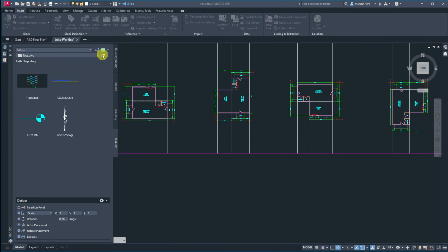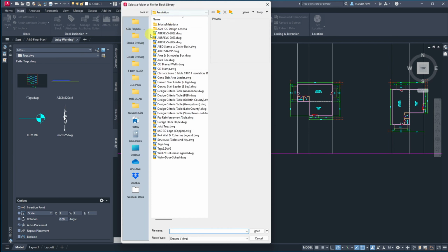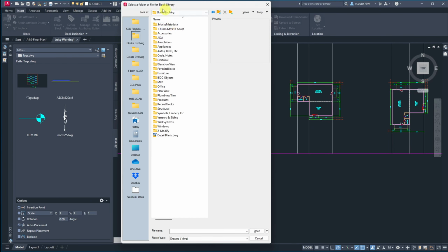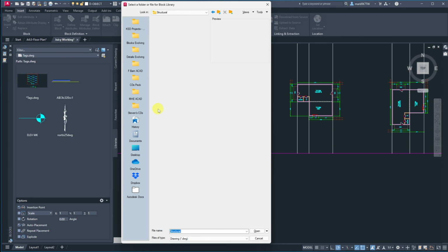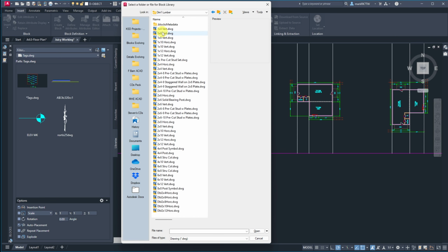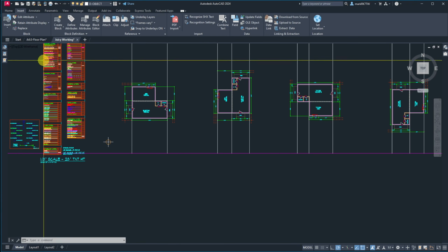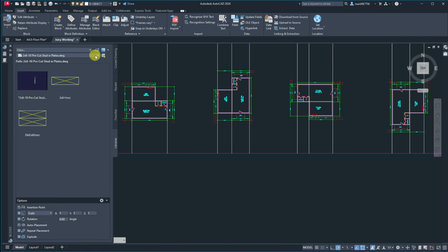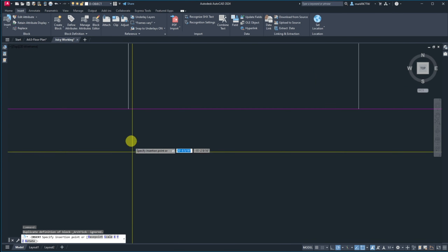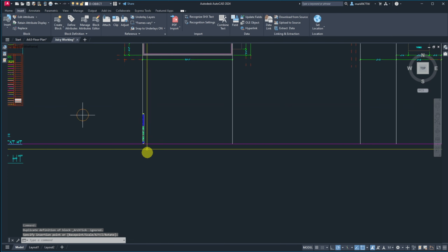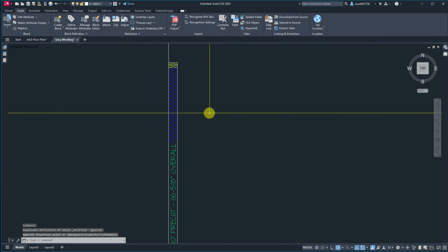So nothing was there, so I'm going to go to library, which now I'm going to take it to the same place. I'm going to back up one because this is that blocks folder. And then I was in structural, dimensional, and then 2x6 pre-cut, not the 2x4, the 2x6 pre-cut. And now, if you use it with the library symbol, you'll have to select it to bring it in. So now I'll bring it in, drop it, and now I've got a pre-cut from my floor system.